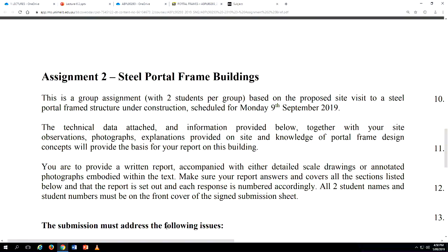There is a question, for example, on what the base plate looks like. You can virtually draw a column, put a base plate, and then when you go to site, you just say this is 6 M12 or 6. The M12 or M24, M32 is already given to you, but the number of bolts is not given to you. That's why when you go to site, please make sure that you take note of the number of bolts. If you look at the brief and the additional data sheet, which I will show you shortly, that is not there.